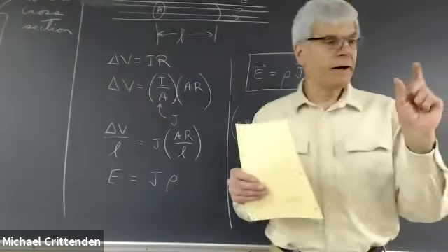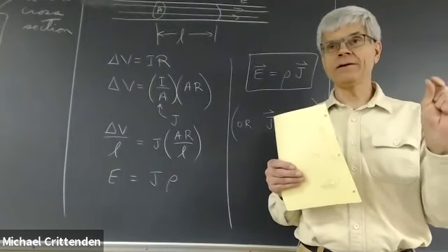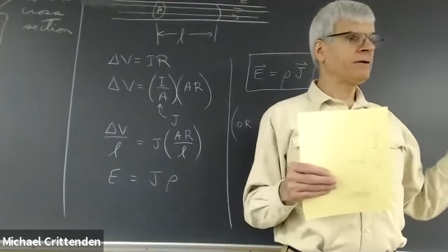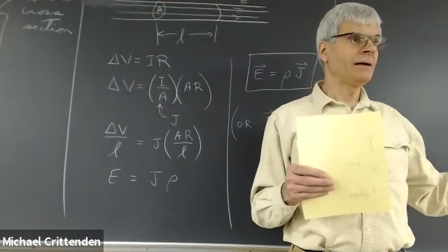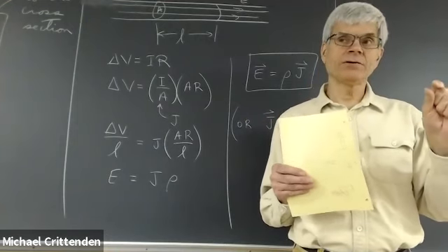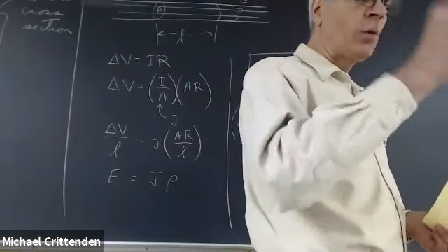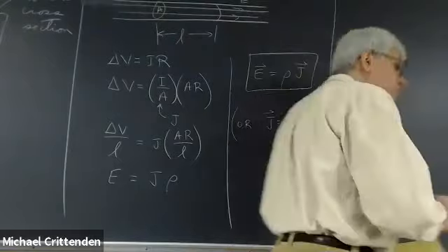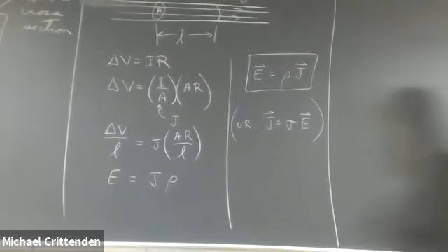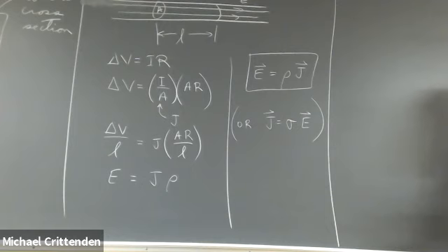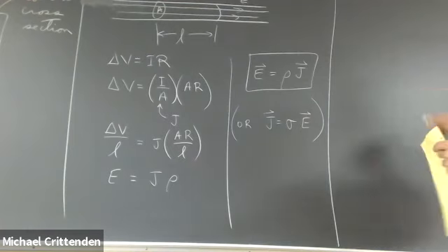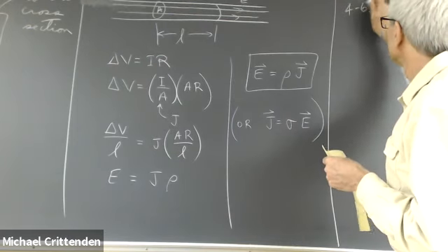So you can buy wire, of course, in all sorts of different thicknesses. If this is the material and this is the number of ohms you need, what diameter should you have for the wire? And then, of course, you have to find some place you can look up what wire gauge corresponds to. I don't know why they can't just sell wire by the diameter. That's what they do with pipes. But they have this secret code about this is 14 gauge wire and this is 16 gauge wire.